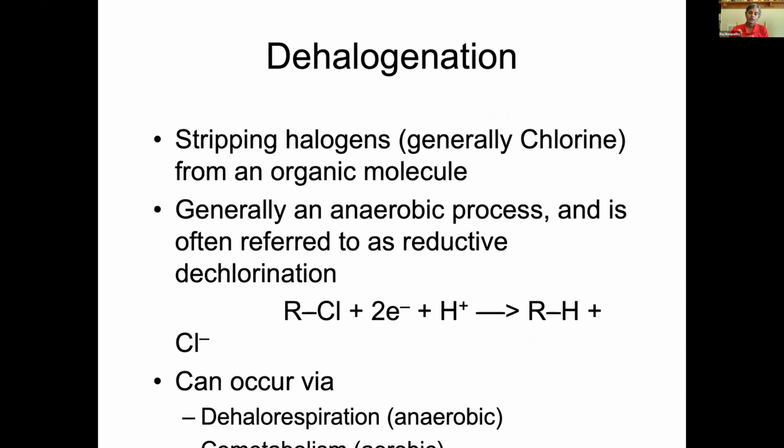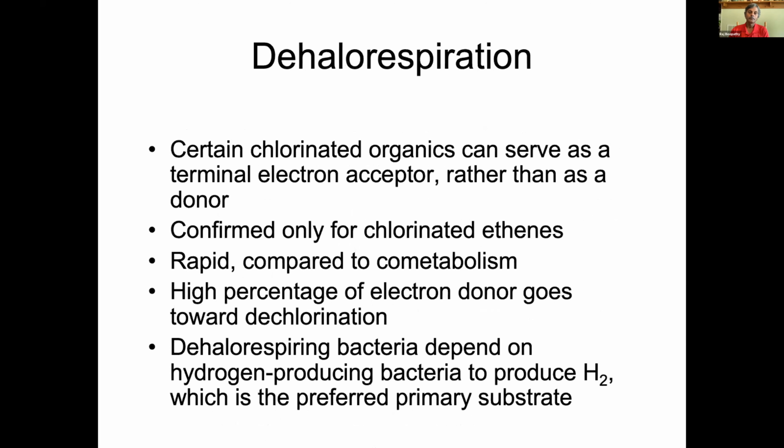Then in the anaerobic condition, one of the common ways bacteria degrade is the dehalogenation reaction, where wherever there's chlorine, bacteria reduce them, substituting the chlorine with hydrogen, which is the electron. So the compound itself is acting as the electron acceptor in the dehalogenation reaction. We have dehalorespiration, so you need to provide enough electrons. Sometimes bacteria get electrons in nature from other organisms when they degrade compounds, but you need to have enough electrons for the organism to reduce the compound.